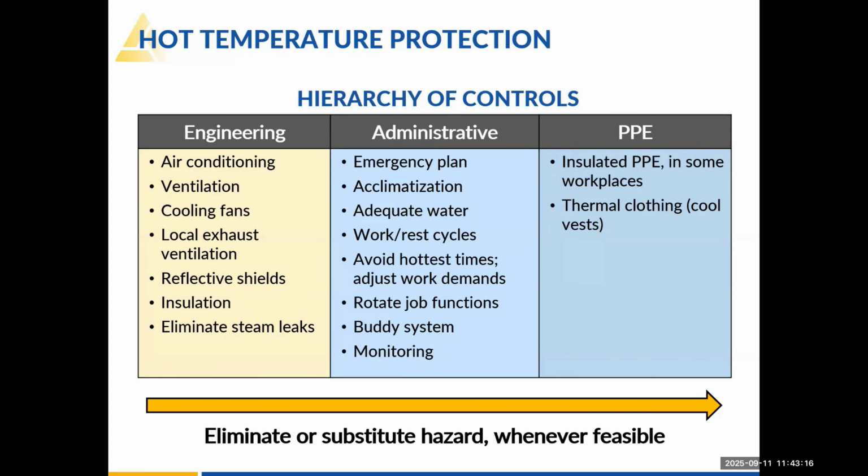And same thing administratively. You'll see a common theme here, but adjusting work-rest cycles, acclimatization, making sure that workers get used to that heat before working in it. Another good thing, rotating jobs, adjusting work schedules to avoid the hottest times of the day, would be just a couple examples there.